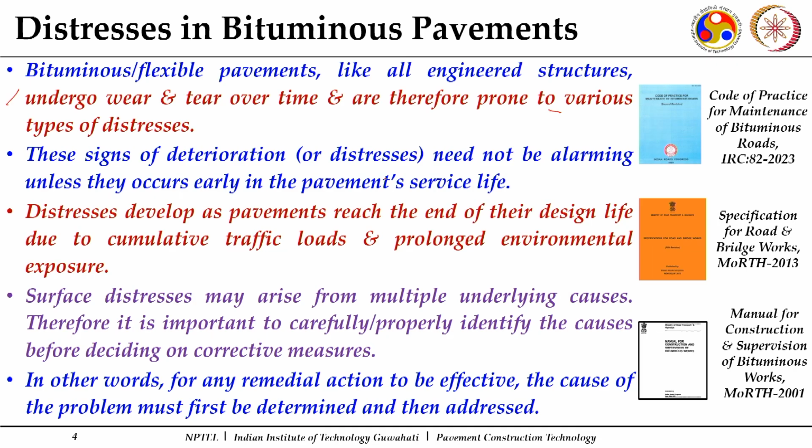And these signs of distresses, some fine cracks, some loss of fine materials, may not be an alarming one unless they occur prematurely in the early years of the life of that particular pavement. So, premature distresses are the major concern for the engineer. Distresses develop because it is an engineered structure which is subjected to different environmental conditions and traffic loading during its course of service.